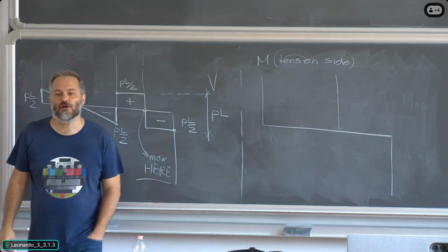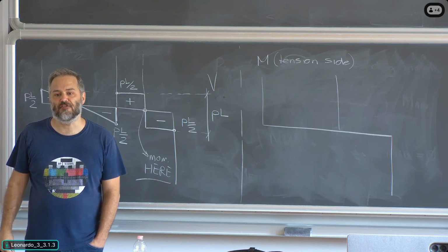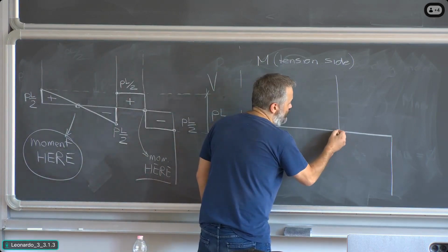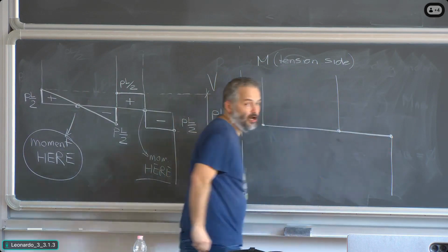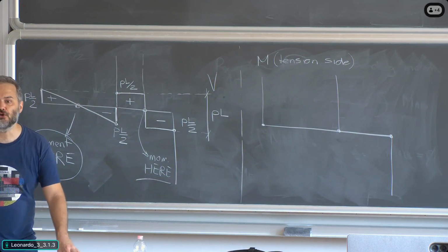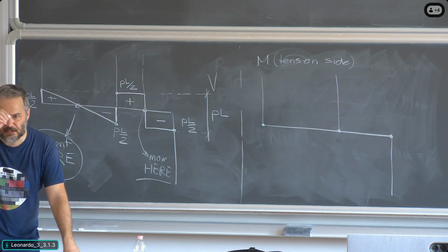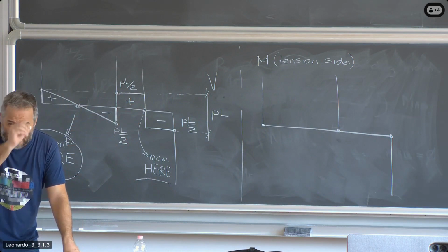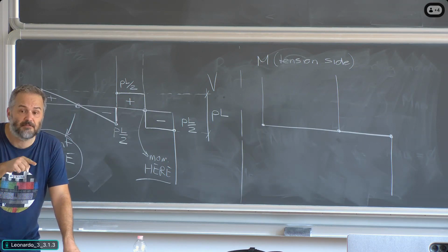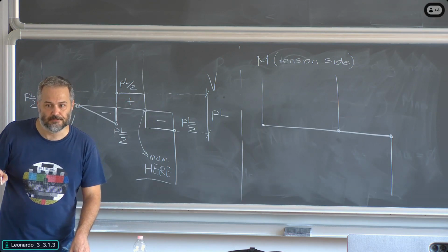Let's fix the values we already know of the bending moment. Where are they? The hinges at the ends of beams AB and BC. So this point and this point all have zero bending moment. Got it? If you have a solution where the bending moment is not zero at hinges, I mean hinges which look like circles, not the half hinges for the continuous beams, okay? Hinges like in this case, and the bending moment is not zero, you have something wrong. You have to check your results because something is wrong.